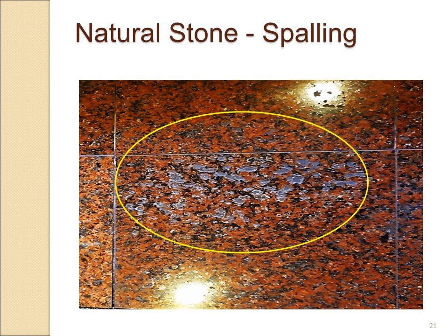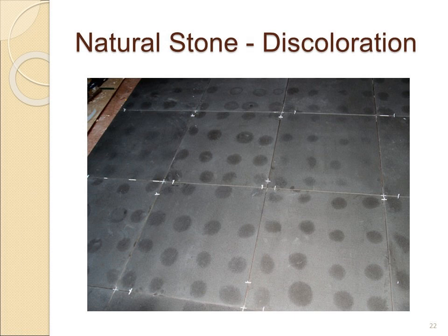And so depending on how we treat moisture, sometimes we can even six-side seal stone with special types of sealers in order to help keep moisture from affecting the stone. It's never something that you can 100% guarantee, but it is something that you can consider. We all know that stone can show some moisture through.